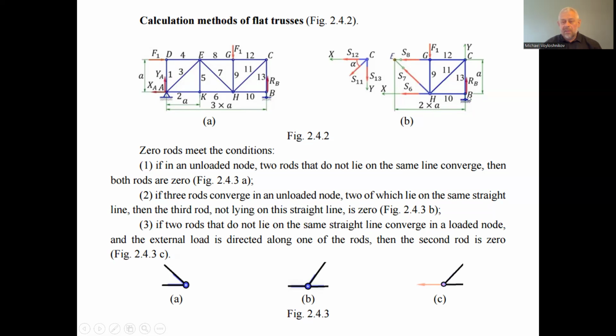For example, we consider the balance equations around the reference point B. It can be the reference point of any coordinate system, like y, x, for example, or the point of determination of the rotation moment around it. For a separate rod in the truss, we do not consider the bending moment, but for discs consisting of rods, we can consider the rotation moments caused by acting forces in the cut rods when we do, for example, the section method.